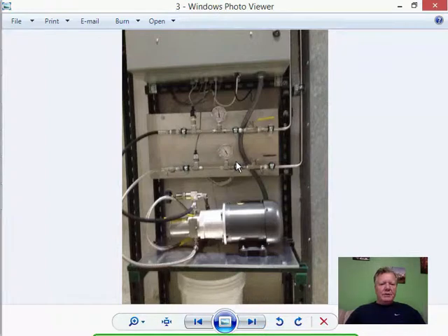You can see there's a couple gauges on it, input gauge, output gauge, couple of ball valves, pressure transducers, transmitters right here, low pressure and high pressure for alarms, water regulating valve, and this is the pump itself. It's a Danfoss pump. The system happens to have DI water running into it, very clean water, bell housing and motor.